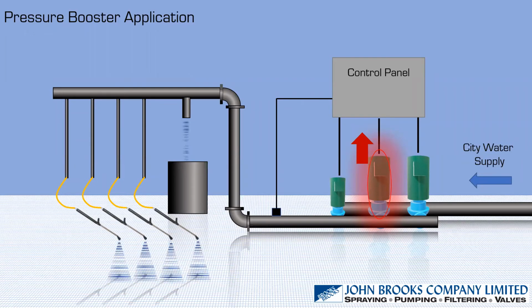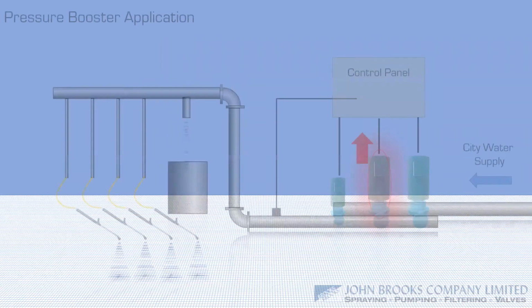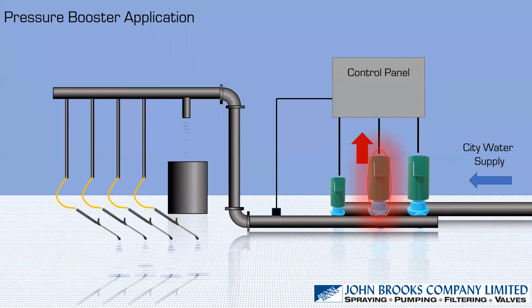Yeah, that's right. Hey, Steph, we've got a question here that's worth covering now, I think. Okay. Go back to that slide with the back one. Yeah. So basically the question is, if for instance the city pressure is enough to maybe fill that drum that you see there on the right hand side of your system, basically, are there any concerns having the low flow that doesn't require any of the booster pumps? So the flow would come from the city through a non-operating pump. And basically, I'm thinking that he's getting at, if there's enough pressure in the city main to fill that drum, therefore doesn't require the pump to start up.